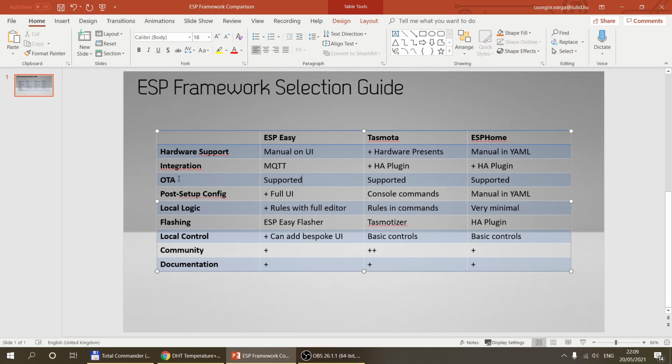The reason I'm explaining all this is that as we start introducing more and more sensors, the code for all of these sensors and the logic and everything has to be included in the firmware. So I think with ESPHome and also with Tasmota, we reach a limit where they have to pick something which is most widely used. So there could be some special sensor that could be supported by ESPHome, but it just doesn't fit in the firmware, or not in the size of firmware which you can upload into certain devices.